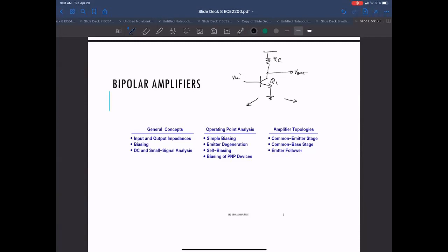One of them was the large signal model, where you have a diode in the base, you have a current source, and you have the resistance of the collector. So this would be the emitter, base, and collector. This is a current source where I_C is I_S exponential of the base-emitter voltage over V_T. So this is a large signal model.